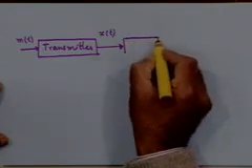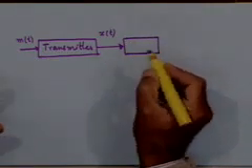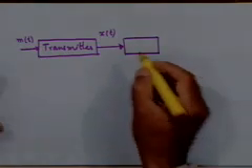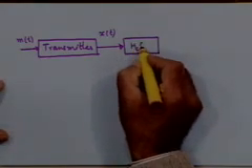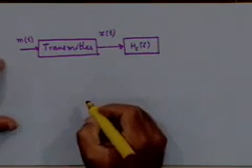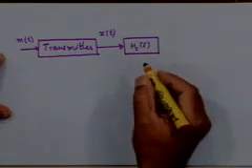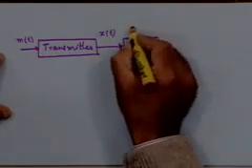It can modify the amplitude of the various frequency components, or it can modify their phase. All these effects can be nicely modeled if you think of the channel as a filter. So a very simple and convenient model for a communication channel, and that's true for every kind of communication channel, is a filter with some transfer function h sub c of f. So this models the channel.